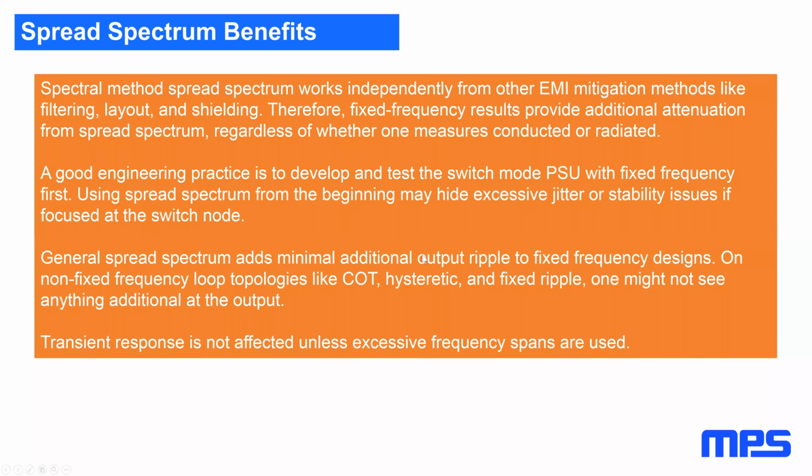You can think, if you have, say, a 1 megahertz switcher, the phase noise at 1 megahertz will multiply by 100 at 100 megahertz. So if you have a typical switching regulator, which has some phase noise, and even COT switchers typically have more phase noise, they give you some natural spread spectrum. However, if you force your system to synchronize on a crystal clock, which has very low phase noise, then this benefit goes away. So synchronizing with a very clean clock actually can damage your EMI performance. So don't be surprised by that one.